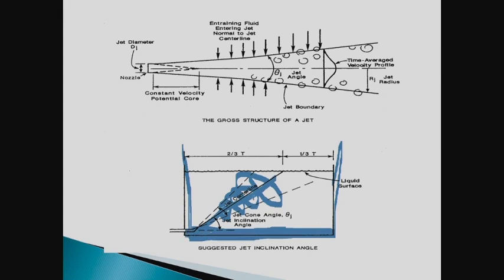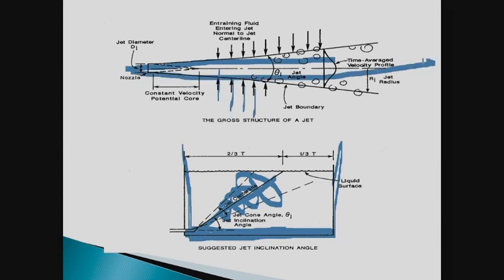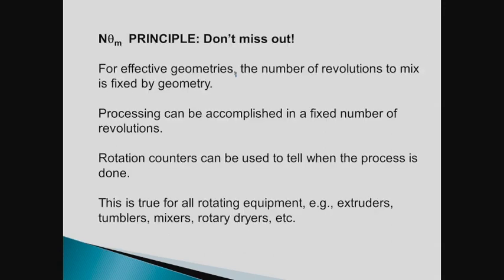Even though you had a good mixing jet, this bottom down here may be a collection of debris. The jet mixes by entrainment, so entrainment comes in from the side of the jet. The total momentum of the jet remains in this direction. It remains constant. Some of the stuff slows up as it speeds up the material coming in from the sides.